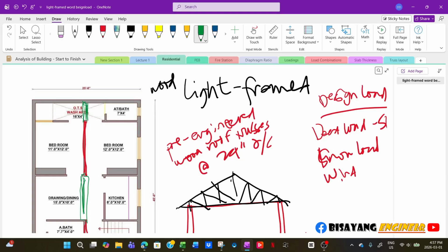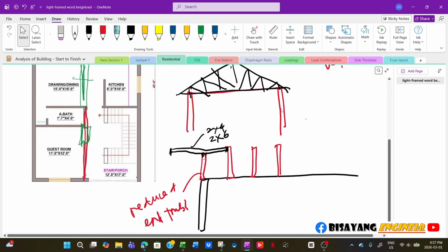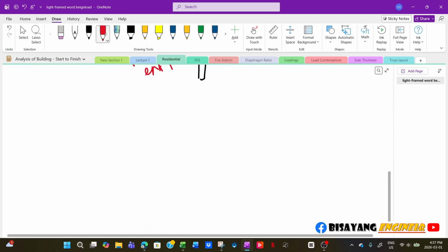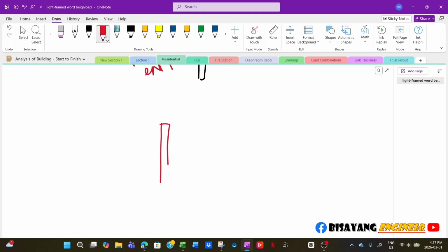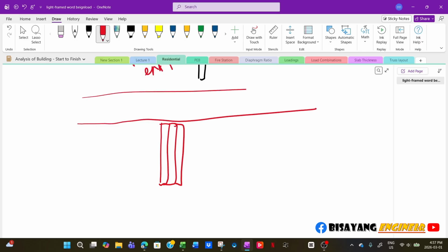To avoid any bulkheads, you can tell the architect that what we can do is a flush joist. What it means is, if this is the beam, regardless of how many plies, one way of framing it is to just run the joist on top.